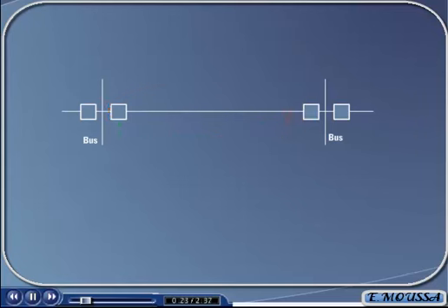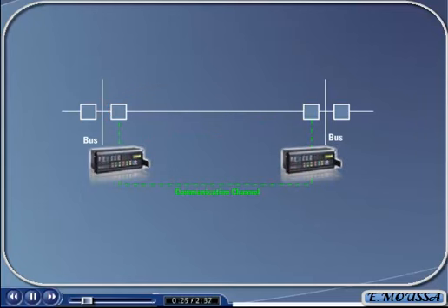As for all pilot schemes, there must be a communication channel set up between the distance relays at each end of the line. This communication channel can be one of many different configurations. The communication channel may have the ability to only send one bit of data back and forth between the relays, such as a power line carrier communication link.